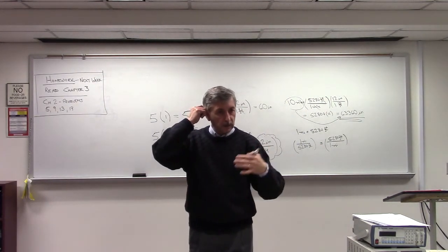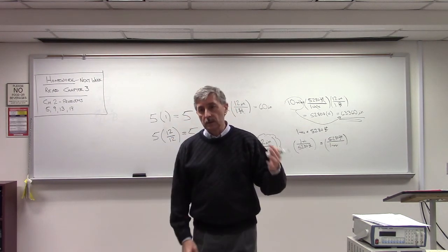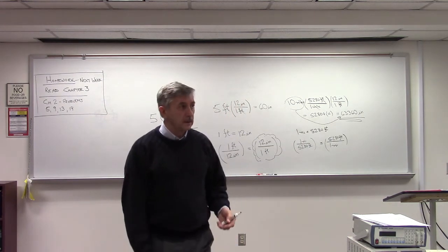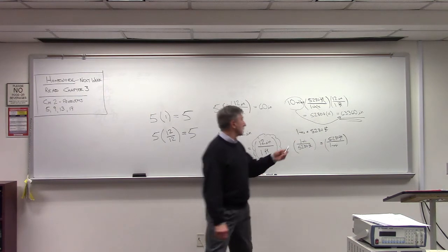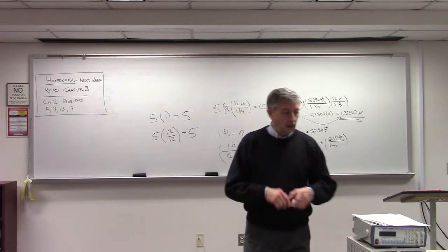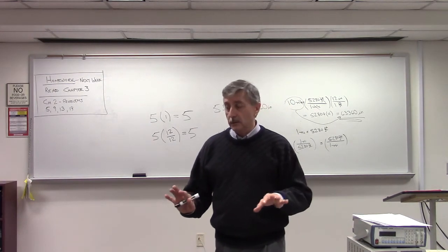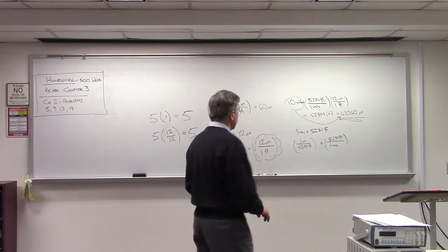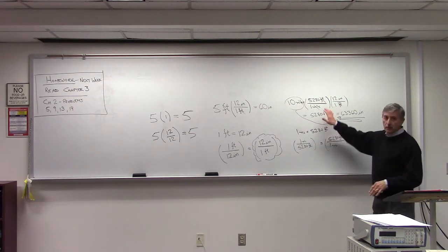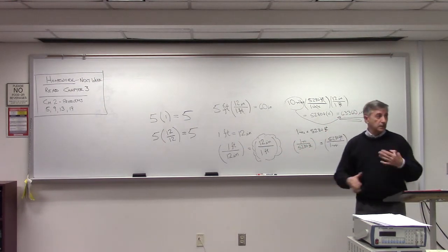And that may seem like a somewhat trivial example, it's only distance. But when we get into ohms and volts and farads and all that good stuff, that is a very useful tool. You get into manufacturer's data books and you start converting units, and you can really get yourself messed up in a hurry. So just remember that all you're doing is multiplying by 1, and flip your fractions so that the dimensions cancel.